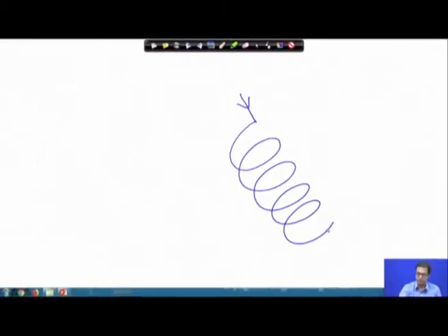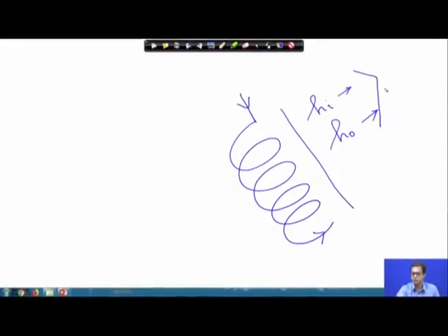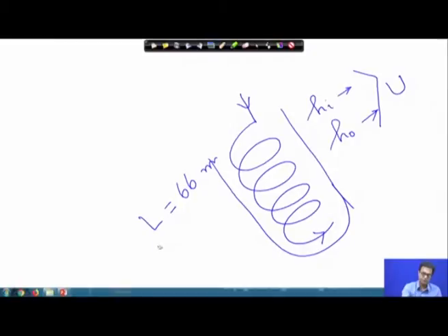It has to be a concentric tube, and we have to make a coil of it, and as soon as you make a coil of it, you will find both its internal heat transfer coefficient and the outside heat transfer coefficient of the annular space will change, and that will of course change the overall heat transfer coefficient. So, it will become a different problem, but we are not going to solve it at this moment. We are only happy with the total length of the exchanger and that has come to be 66 meter around.